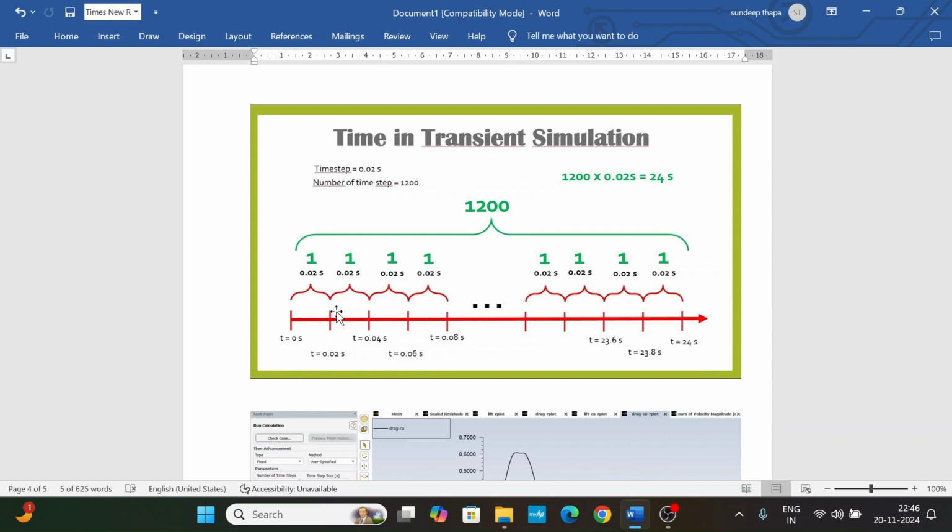To give you enough accuracy to reach the convergence point, below 30 iterations would be sufficient. You do not need to go for 1500 or 3000 iterations, even for more complex problems. Between 30 and 50 would be sufficient. From 0.02 seconds to 0.04 seconds, nothing major has changed.